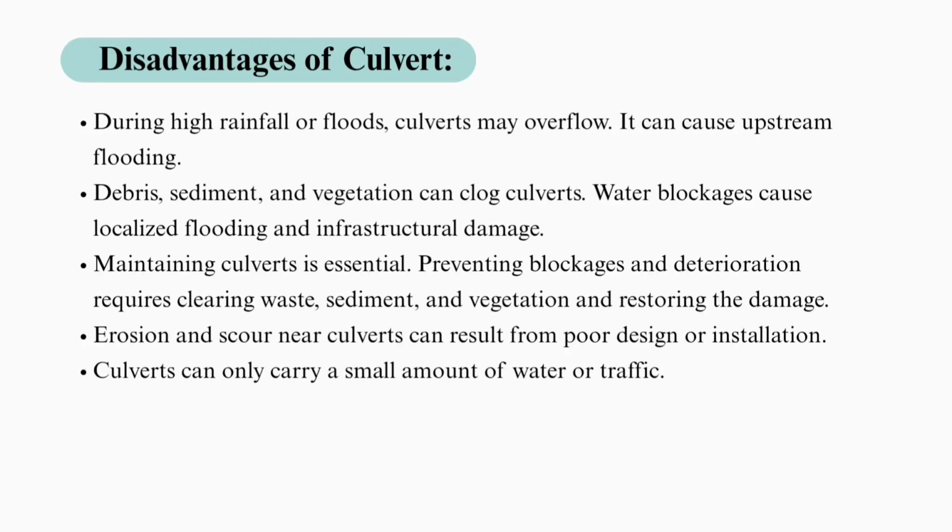The next is disadvantages of culverts. During high rainfall or floods, culverts may overflow. It can cause upstream flooding. The next, debris, sediment and vegetation can clog the culverts, and water blockages cause localized flooding and infrastructural damage.